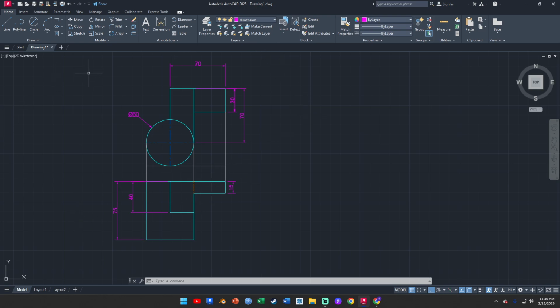So now that we have that information, now that we know which one is the front and which one is the plan, we can actually start constructing this in isometric projection. So as usual, I'm going to start off with the default layer, and you don't need all of these layers that I have here. I basically just use them to do the orthographic projection, right? Most likely you're just going to need the default layer and the outline layer, right?